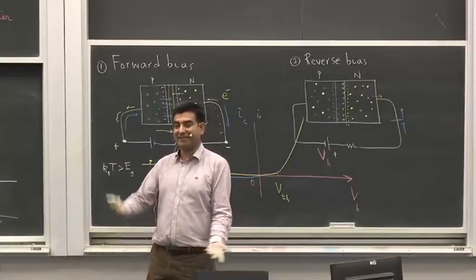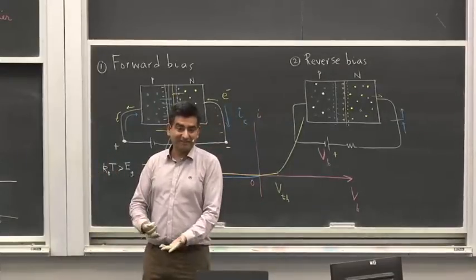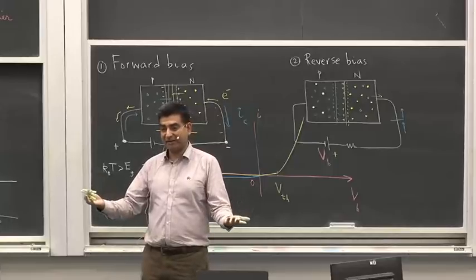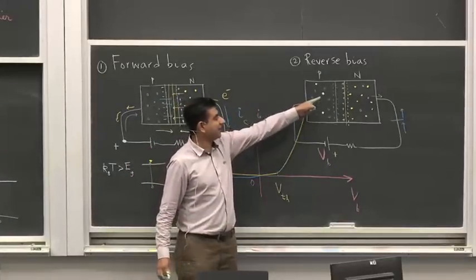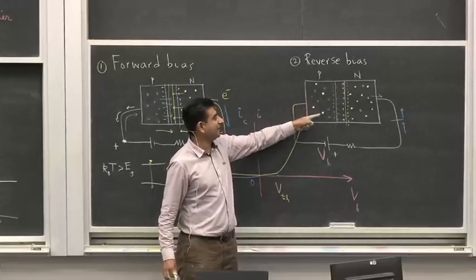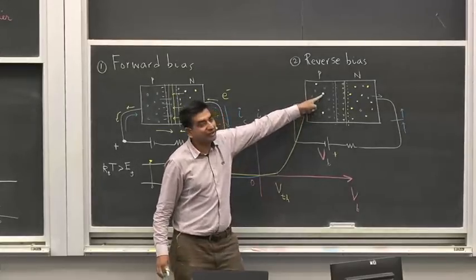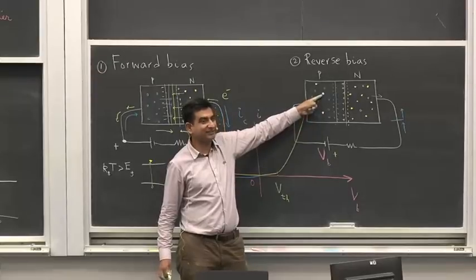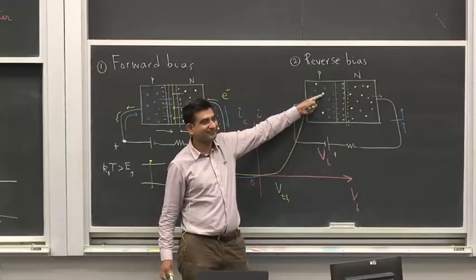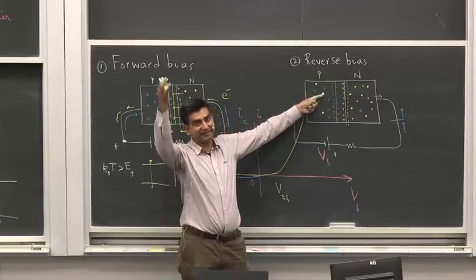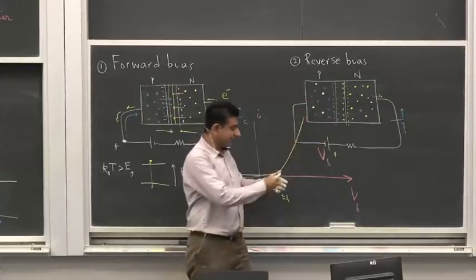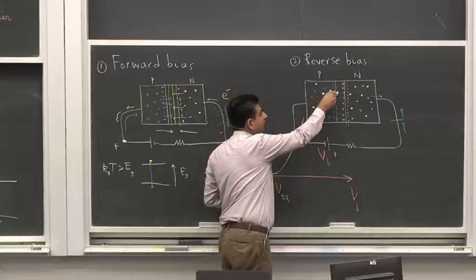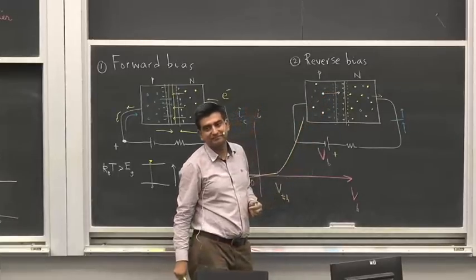In a p-type material, electrons will be created, and in an n-type material, holes will be created. So there are always some minority charge carriers. Look at this minority electron inside a p-type material. It has been thermally created. See the negative terminal of the battery. This electron is being repelled, so it moves towards the junction.